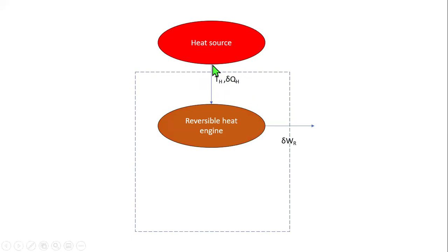But if we keep it like this, what we are saying is that all the heat that is coming in is being converted to work, and that is not possible in reality. So not all the heat that is coming in can be converted. Some of the heat has to come out, right? So we represent that with del QE. There's some amount of heat that will also come out, a small amount of heat being transferred, and it comes out at its own temperature, right?